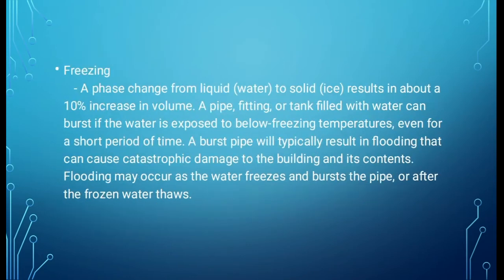Next is freezing. A phase change from liquid or water to solid or ice results in about a 10% increase in volume. A pipe fitting or tank filled with water can burst if the water is exposed to below freezing temperatures, even for a short period of time. A burst pipe will typically result in flooding that can cause catastrophic damage to the building and its content. Flooding may occur as the water freezes and bursts the pipe or after the frozen water thaws.